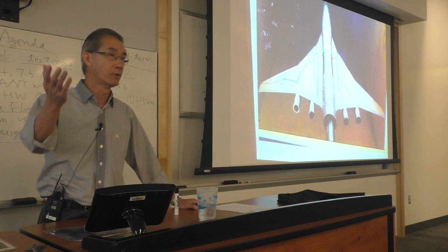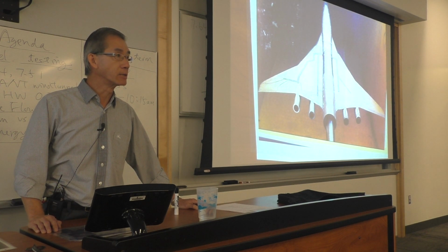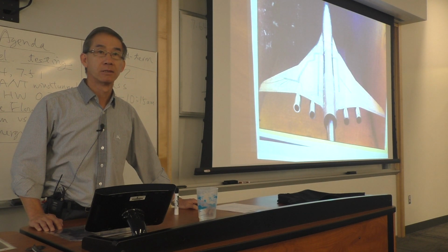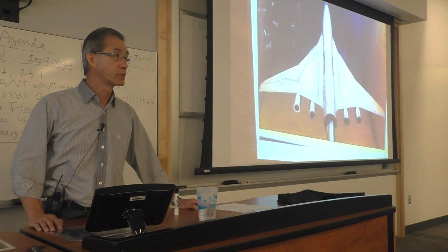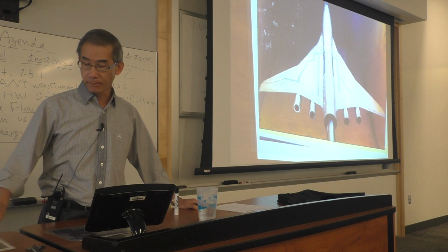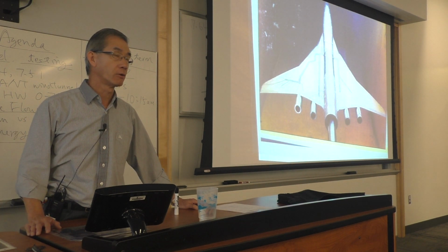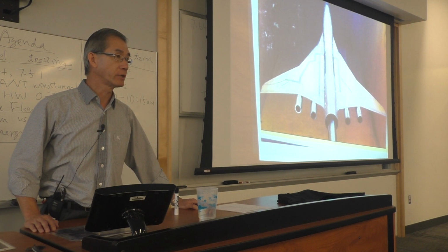And this is something, if you work for Boeing or Pratt & Whitney, that you need to know. Right? So what is the pressure being read on this tiny hole on the wing surface? Still no clue? It's a static pressure, undisturbed, just like the hole on the pitot-static probe, that is not being perturbed by the flow or disturbing the flow. So by measuring those pressures on the wing, on both the pressure side and suction side, you can also check the lift of this model. And that's how an experiment is done. Get a feel for this?